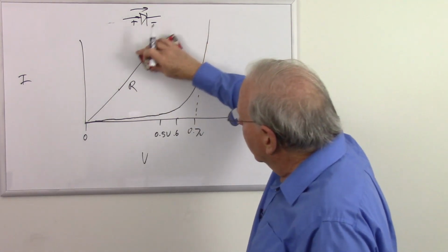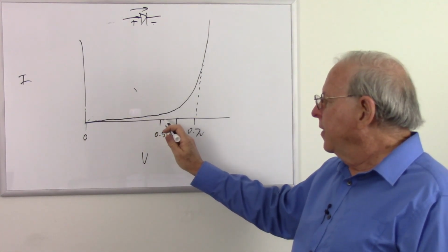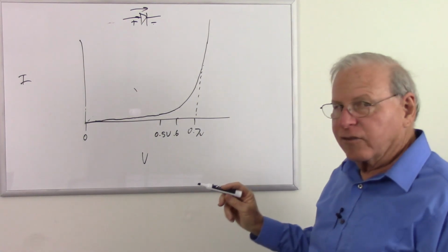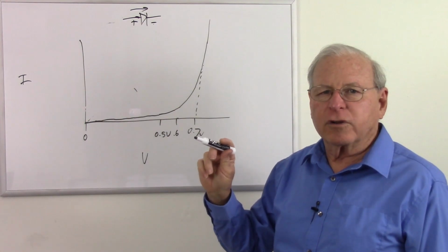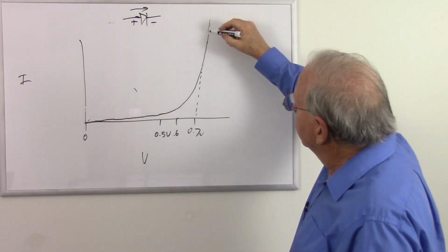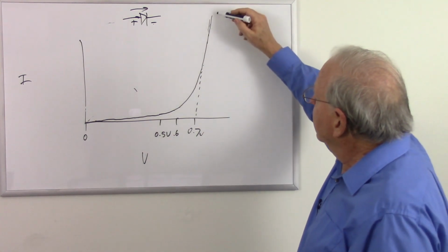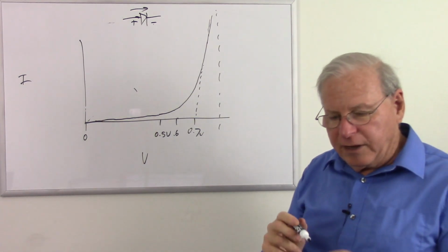We get this logarithmic curve where no conduction, no conduction. At about 0.5 volt, it starts to conduct, and it's really conducting at 0.7 of a volt. Now, it's a myth that a silicon diode always has 0.7 of a volt across it when it's forward biased, because this is not going straight up. It's going at an angle. And if we go higher, we'll find it is more than 0.7 volts. It depends on the diode.